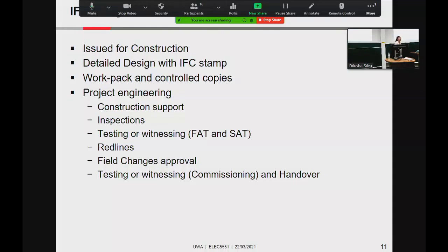So what they do is, on your design they use a literal red pen, that's why it's called red lines, and they cross off the dimensions and redo them. Imagine if you were to issue multiple copies of the same drawing, how would you control those copies? That's why there are controlled copies with sequence numbers listed. We can print all we want, but we receive the red lines, because engineering receives those red lines. So it's important for us to understand what it means. The controlled copies are issued and used for construction red lines.